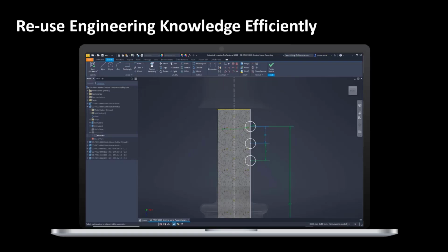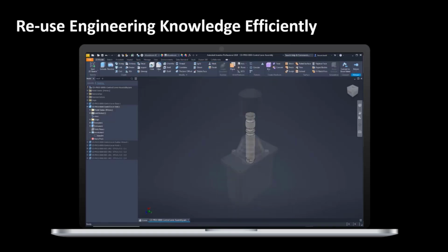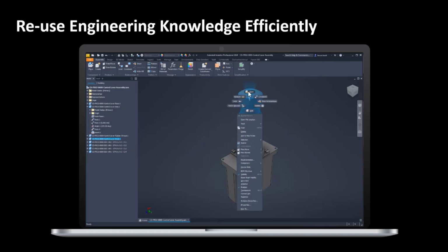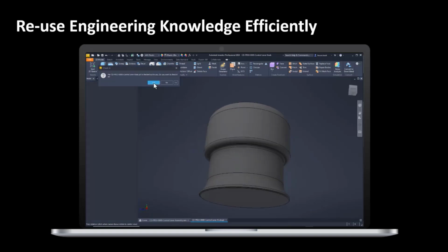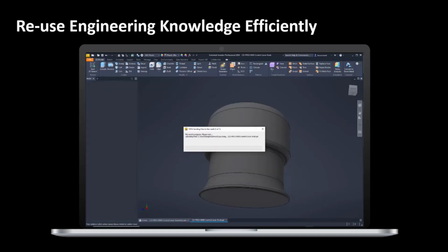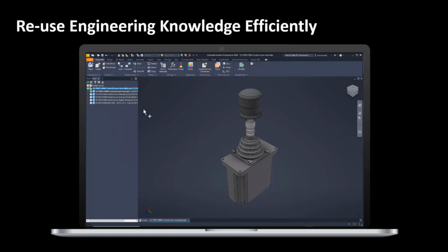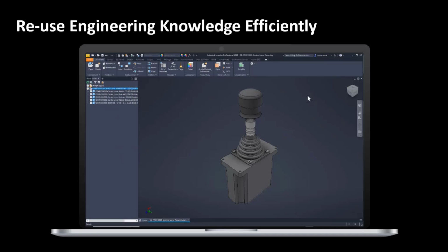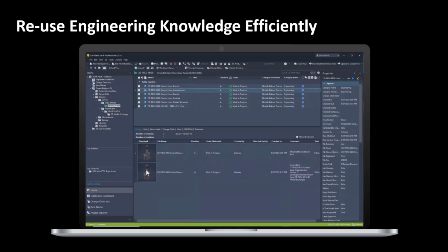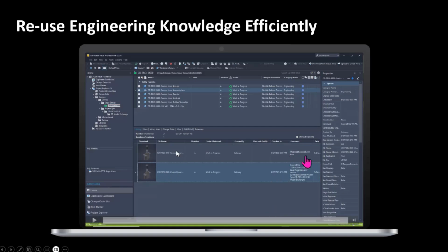Once within a few minutes, we already create duplicate assemblies with new file names and new relationships that are not going to go back to the original files. So like in this case, this knob, make some changes a bit here and there. Okay, and then just update. We can put some remarks every time we save. So modify knob and lever just to update the assemblies. Now you can see there's a new version. After copying, it's now modified knob and lever arm.